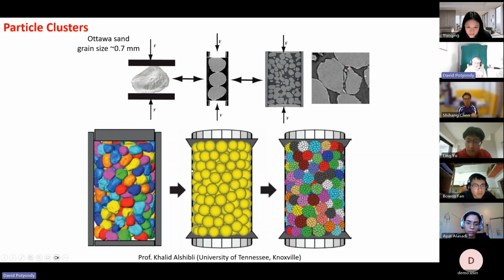They took that centroid and made a PFC sphere that had the same volume. So now they have this packed sphere assembly. And then they said, each sphere is made up of smaller spheres that are glued together. That's a cluster. And so now when we load this, the clusters themselves can break. So if you think of the cluster as a grain, the grain can break. Plus, of course, it interacts with the other guys. Okay. And this is an example.